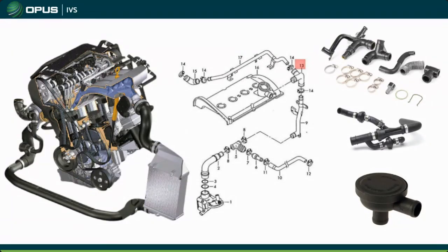But let's move on to turbocharging and supercharging and forced induction, because what that does is change the way that we have to vent this system, because now we have to worry about boost in our intake manifold. We no longer have only vacuum. And so we have to have some way of regulating when the blow-by gases are put into the system, because if we are not careful with that, then we are going to be putting boost into the crankcase, which is never a good thing, right? We're trying to get the positive pressure in the crankcase out, not add to it.